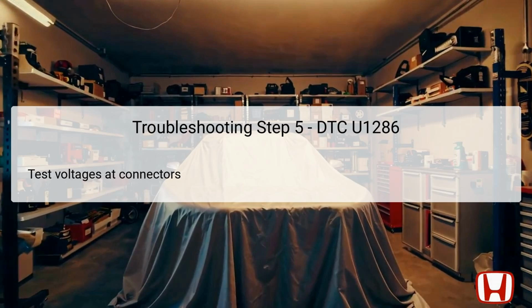If battery voltage is present at these terminals, the absence of communication indicates either a failure within the keyless access control unit or the gauge control module. Conversely, if voltage is not present, it points directly to wiring issues or poor connections that inhibit proper power flow. Accurate voltage testing is fundamental to diagnosing electrical components effectively.